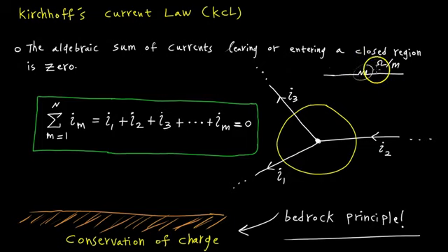With those introductions, I just want to reiterate what this means, why it's important, and what the assumptions are. The assumptions are that there's no voltage drop across these ideal wires, and that at a given node you cannot have a charge buildup. Because if you had a charge buildup, then another node would have a different charge buildup, and then you have what's called a capacitor, or you could have a voltage drop across that wire. It just doesn't add up to the assumptions that we've made. We'll get into more details and more examples later on, so I'm trying to give you the introductions here.